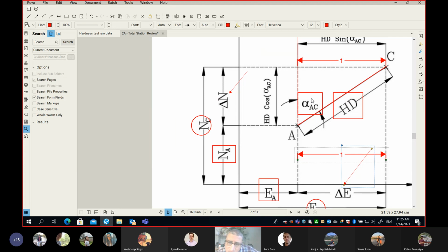And the backside is something very simple. You have 2 control points on site, like traverse points, where you know the coordinates at the end of the line. And from the coordinates, the total station can estimate the azimuth and can rotate the compass to make the reading equal to the azimuth.